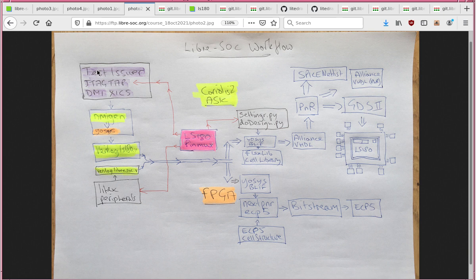That is in Nmigen, so it is handed to the Nmigen compiler. Nmigen compiles that to a Yosys RTLIL file, aka ilang file, intermediary language. Yosys then picks that back up, reads it in and converts it to Verilog, and this is all under the control of Nmigen. Nmigen then saves that as a Verilog file, which we chose to call ls180.v.